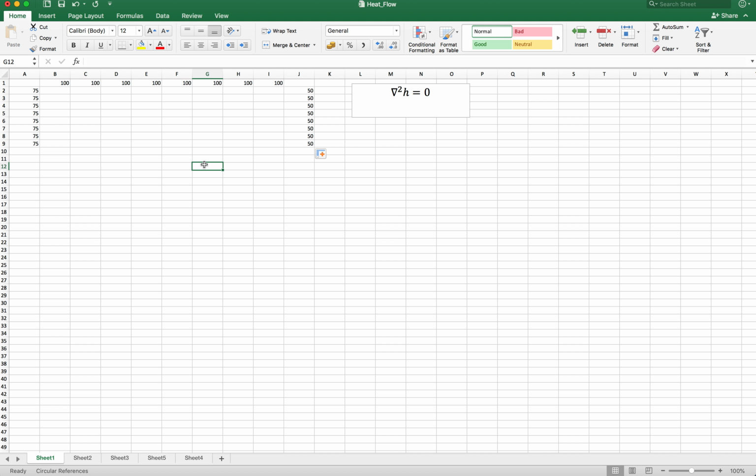And then if you recall, we also did some measurements at the southern end of our site, and we discovered that there was no flux across this boundary. So that means we have a Neumann boundary at the southern end and Dirichlet boundaries around the site. Okay, so that's going to have some implications later on, but let's see how we can use Excel to solve